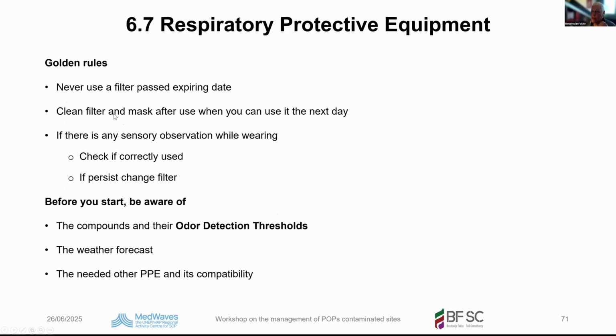The golden rules: never use a filter past its expiry date, clean filters and mask after use so you can use them the next day. If there is any sensory observation while you are wearing it, check if it is correctly used. If it persists, change the filter. Before you start, be aware of the components and their odor detection thresholds, the weather forecast, and the other PPE needed and its compatibility.